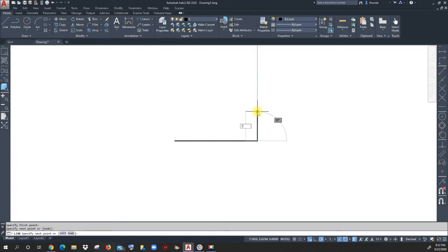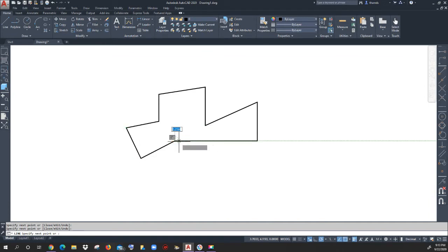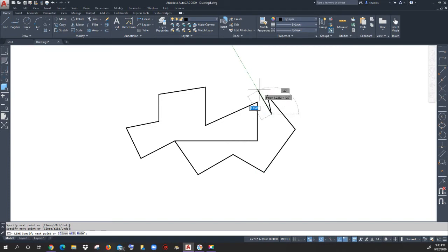If you hit enter, you've drawn a 2-inch line. Now notice that we can click still just like we did before by using our cursor. Now notice whenever I get near a line, I get these little shapes that pop up. We'll come back to that in just a second. Our polar snap makes a snap at these different angles.